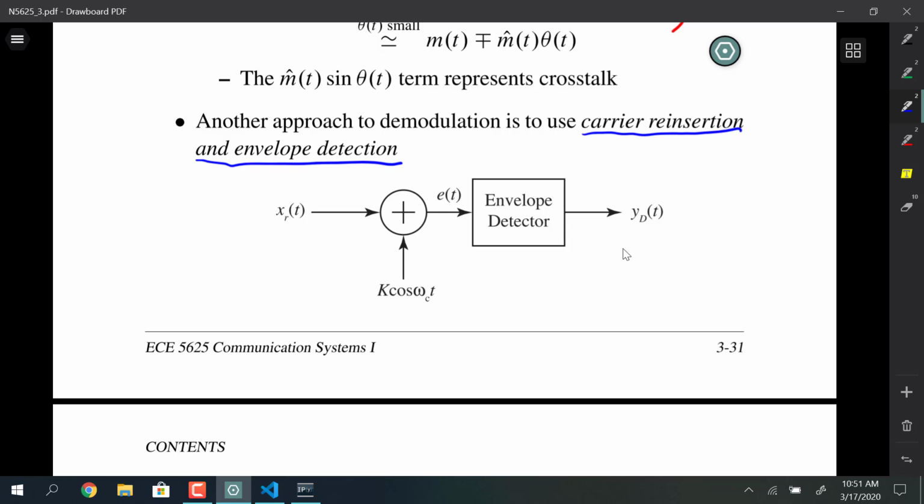And I just want to walk you through it because it shows you how you can use an envelope detector, the diode envelope detector or something similar in software, and also the technique of analyzing the envelope of a signal that has another inserted signal. We'll be using that a little bit later in this lecture when we're looking at interference in AM radio systems.